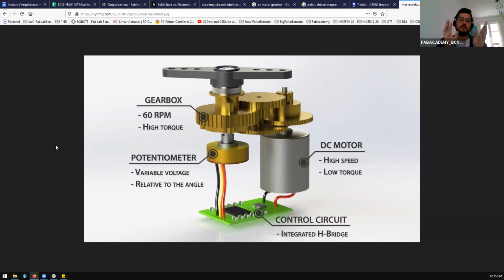What it will do is, you have seen the servos jittering, moving like this in a certain position, a little bit, like shaking. Cheap servo motors do that, because actually a servo motor is never off. What it's doing is changing the polarity, back and forth, of the DC motor all the time. Why? Because we don't want to move the position, but we don't want the motor to lose the position either. So we are applying force all the time, really fast, changing the polarity of the motor, and that allows the motor to stay in the same position with torque.